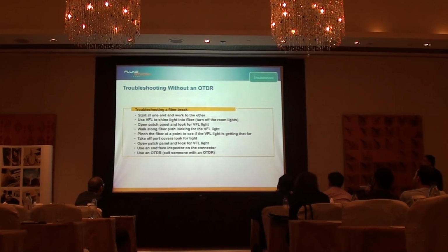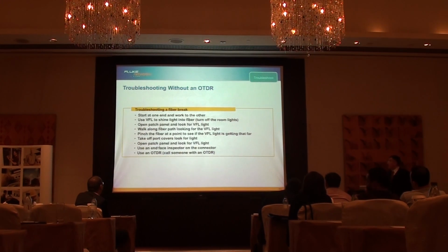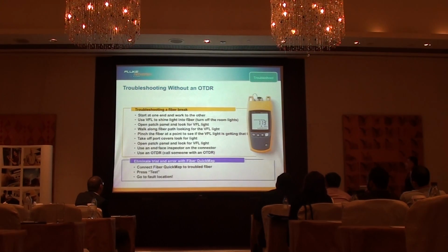So you can work your way, you can figure out the polarity, then you can look at the, basically walk in the fiber and see where the light is coming out. Pinch the fiber, and for the break, you see the light will shine out. So you can see all of these things, and OTDR is the best solution at the end of the day for basically trying to troubleshoot. All right.